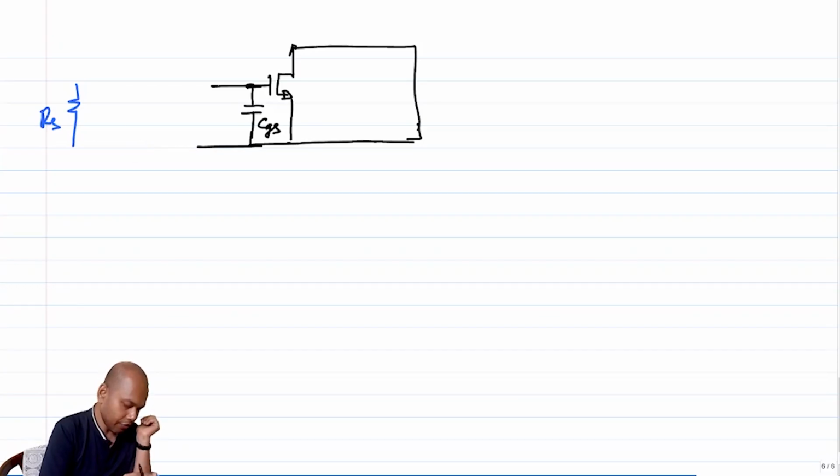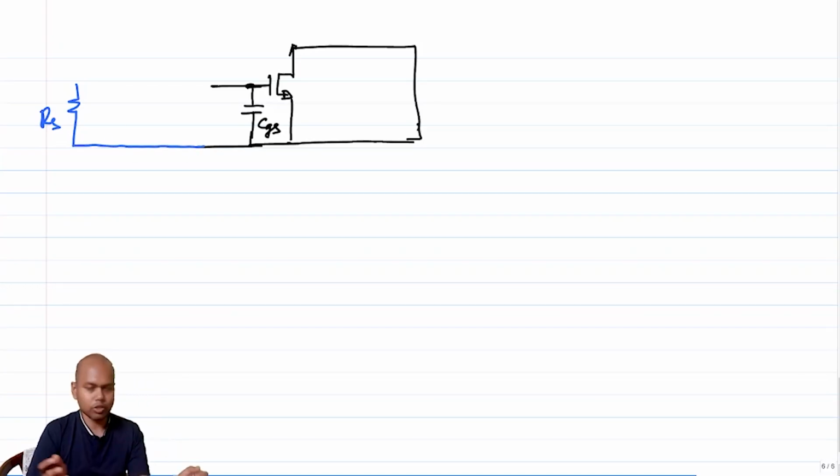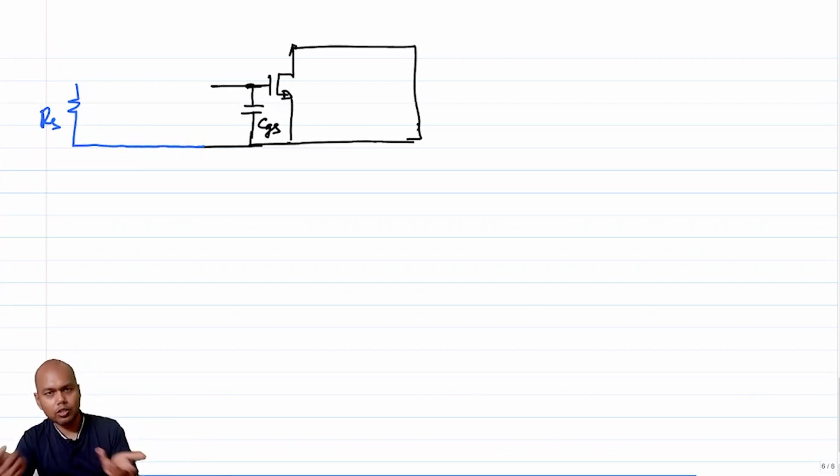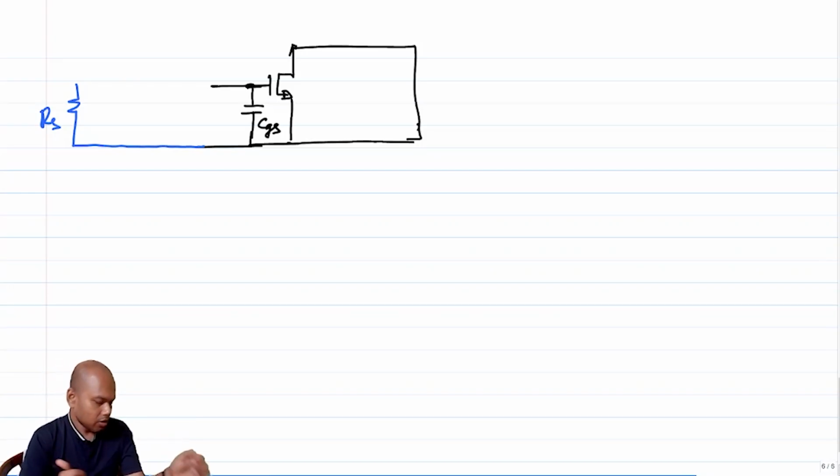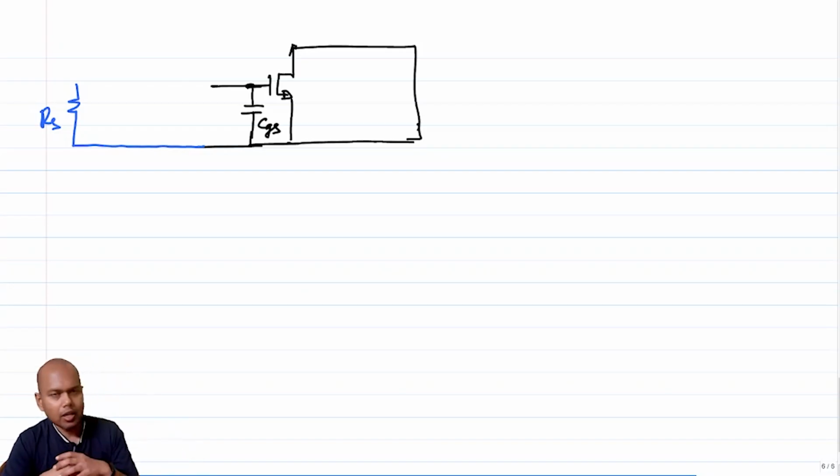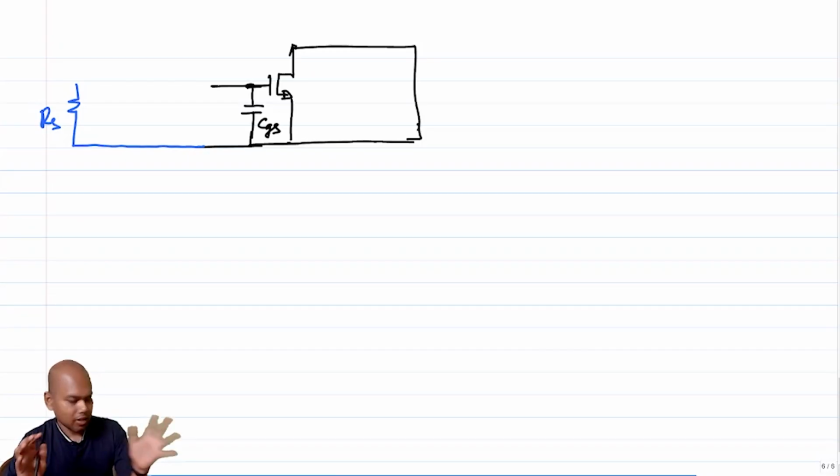I am not including the VI in this model because ultimately VI is a signal source, and the noise source can be tackled using superposition. So I am desensitizing the signal source. I am keeping the RS. Okay. So if you recall, in case of a resistor, we could replace the noisy resistor with a noiseless resistor and a voltage source in series. So in this case, we would like to replace the noisy transistor with a noiseless transistor and a voltage source. Correct? So let's do that.